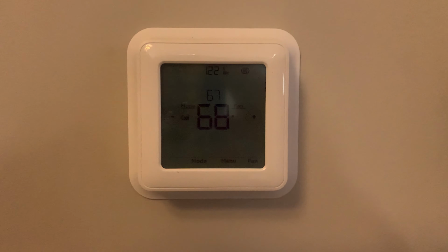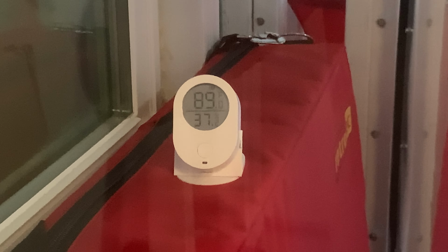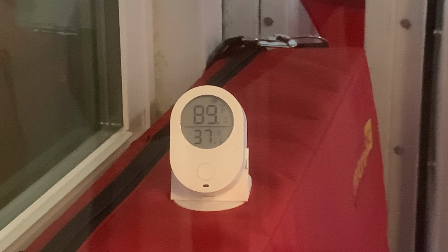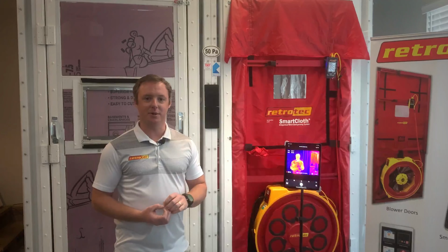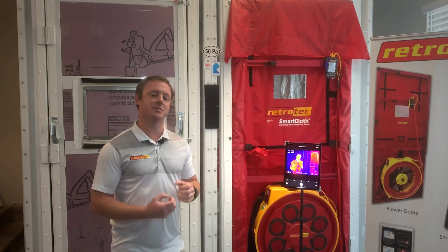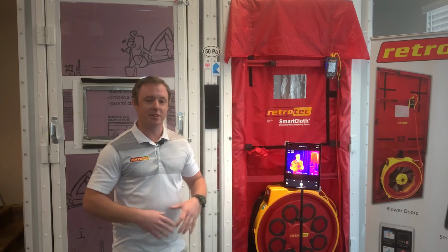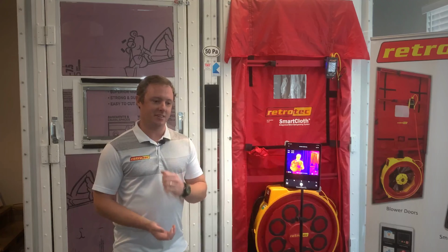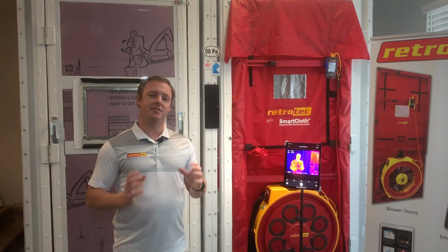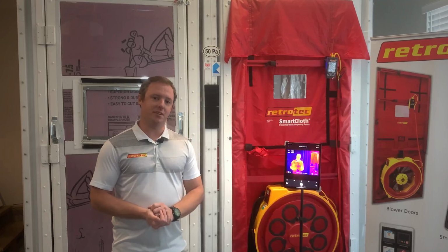Now notice that we have this space inside warmed up to about 89 degrees. Now I know nobody heats their house that warm, but the actual temperatures don't matter nearly as much as the differences between those temperatures inside and out. So within this laboratory setting here, that was the easiest way to create that delta T. That way we'll see those air leaks similar to what we would see in the field.